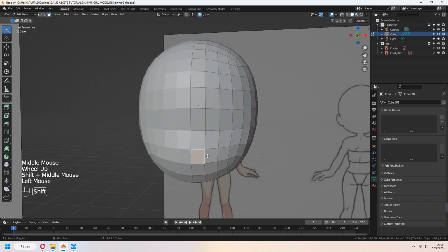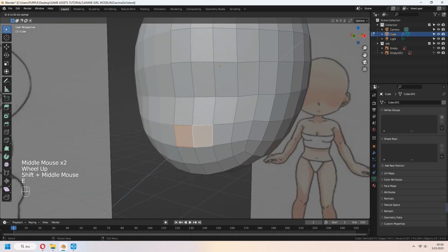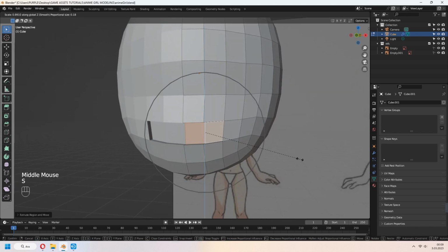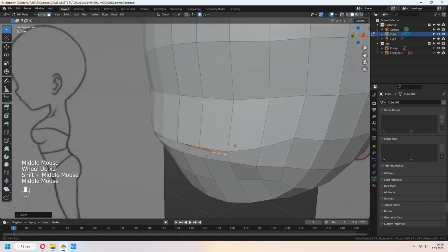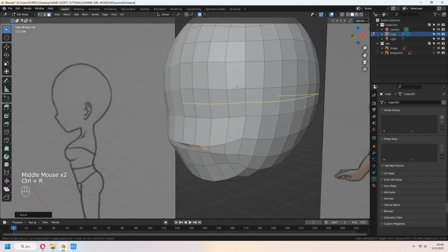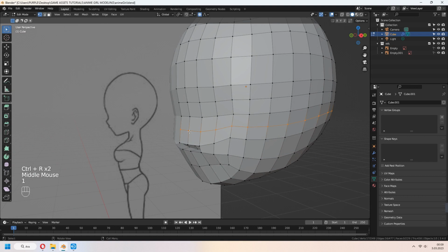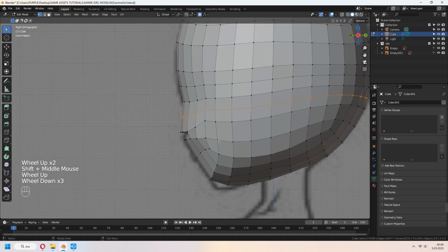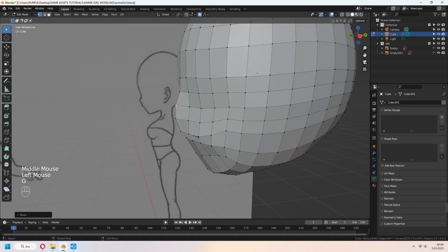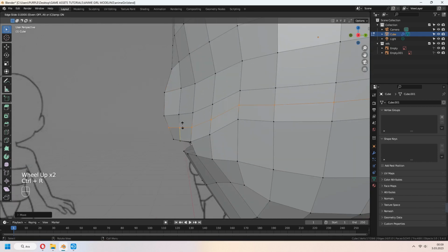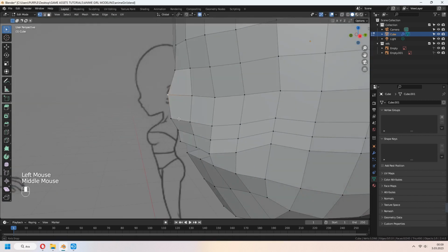Select your faces. For mouth, E to extrude in Y-axis and S to scale. You can add another loop cut if your vertices and shape is not enough. Move your vertices for nose. You can make smaller for your proportional edit with middle mouse.